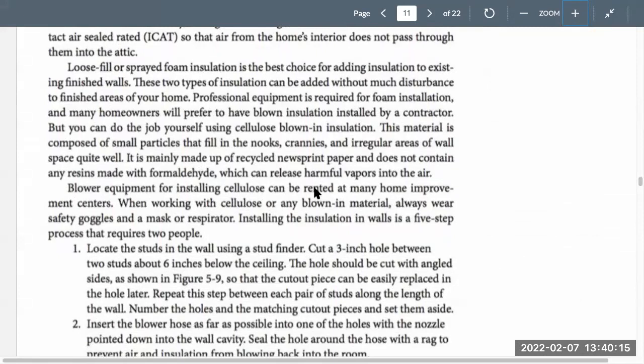This is just telling you the method that we did look at. Some of us may not have seen it, but when we were in the Energy Center, we were in the conference room and we looked at one wall that had no insulation in it, and we felt the hole that we cut into it. Very cold air was blowing through there, as an example of what is going on from an air infiltration point. Then we had one wall right next to it where we insulated the cavity, and on that wall you couldn't feel the air blowing through.